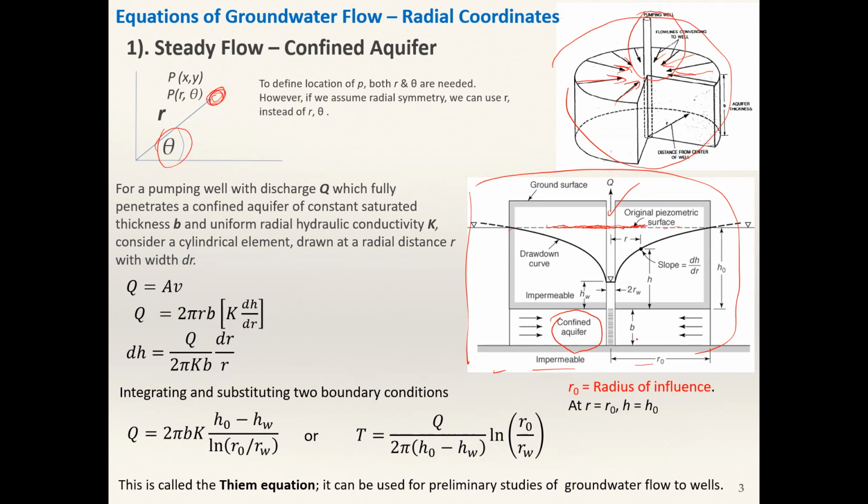And it is a pressurized aquifer, so you can see it only if you drill a well, so that the water level will rise to this level. That is the indication of the piezometric head in this confined aquifer. What is a confined aquifer? It is an aquifer in between two impermeable layers, so it is a pressurized aquifer. If you drill a well, the water level will rise up to this point. That is the piezometric head.